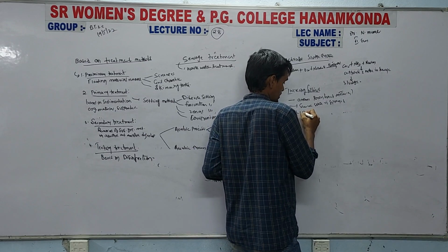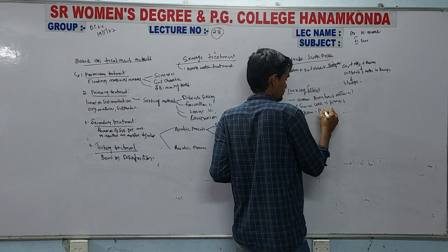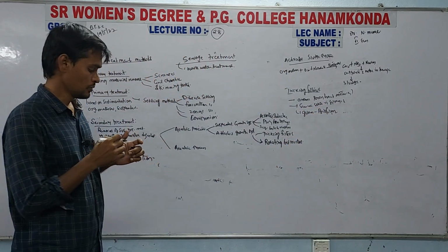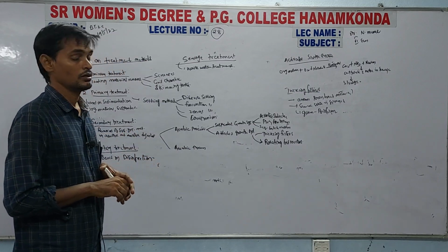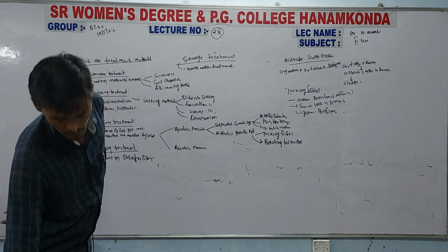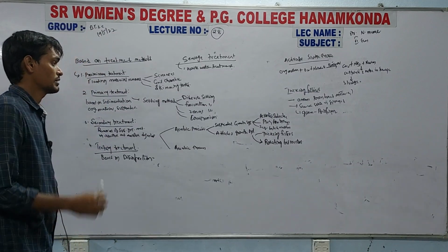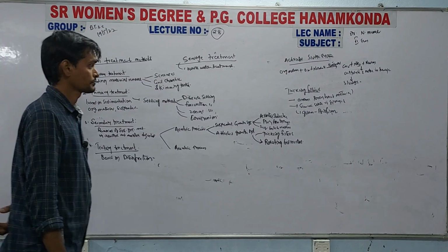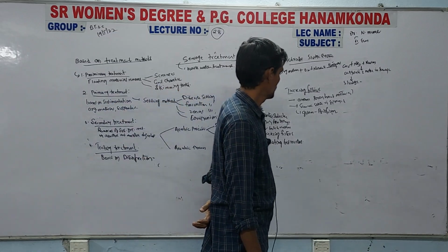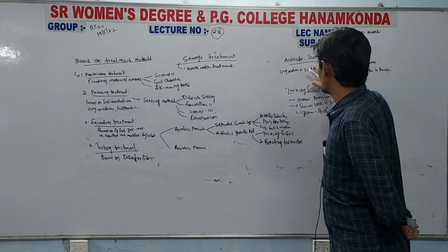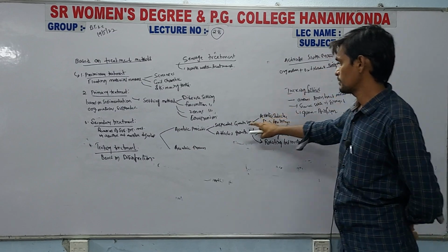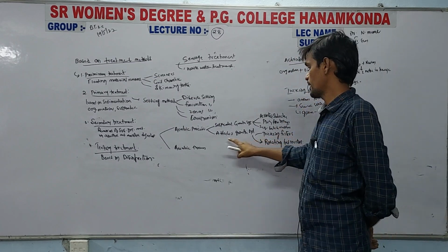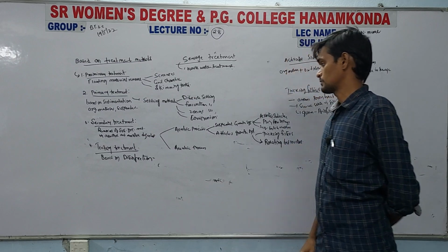After a given time, a biofilm is formed over the surface of the porous hard material, which will be removed as sewage waste. So, activated sludge comes under the suspended growth system of the aerobic process, and trickling filters come under the attached growth system of the aerobic process.